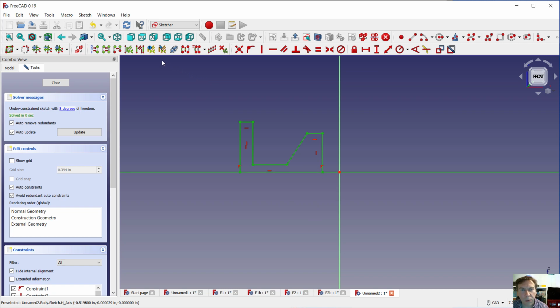Now what we're looking for is the mirror tool, and that's right over here. Now it creates a symmetric geometry, but it does not actually bring over all of the information. Like it's not really truly parametric, so we're going to have to add that. So go ahead and click. Now you'll see it did bring over horizontals and verticals, which is great. But now we have to add those others manually, because watch what happens if we grab this and we click, we get that sort of behavior.